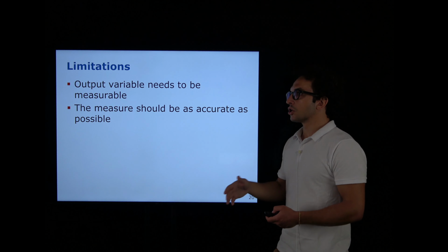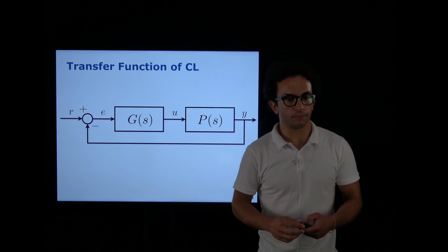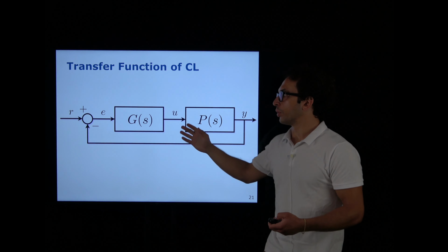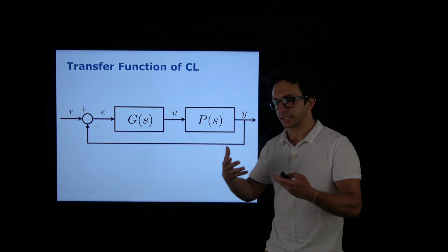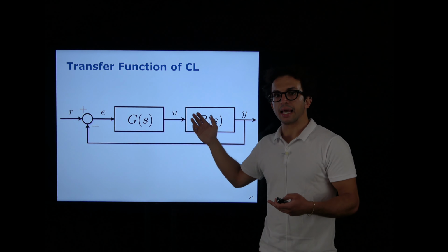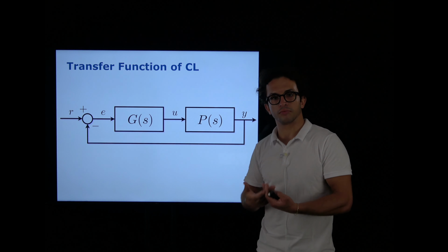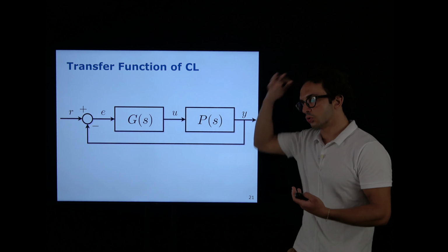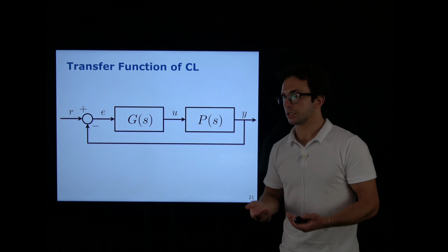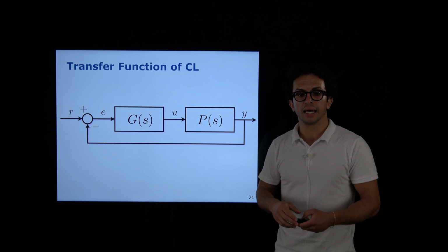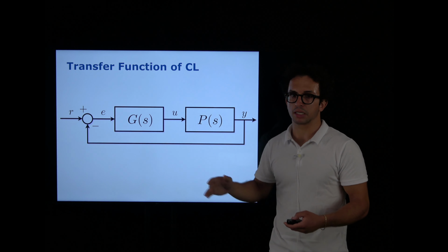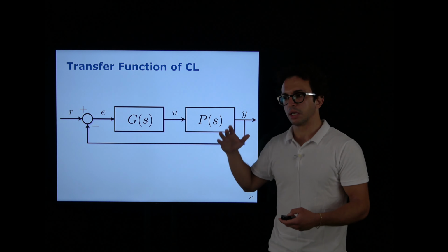Now, let's go a bit forward with the closed loop. In this closed loop scheme, as I said, there are two systems. When we have interconnected systems like this, we have two transfer functions, and the resulting transfer function is just the product of the transfer functions we have. Here we now want to have a look at the stability theory and all of the important quantities that we have for systems, and so we're trying to introduce the transfer function. We do everything for now in the Laplace domain. We'll come to the time domain later for some other specifications.